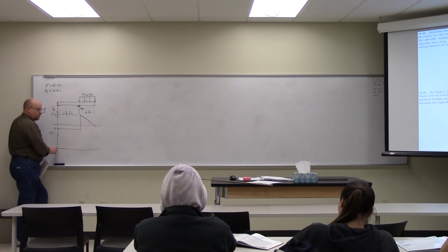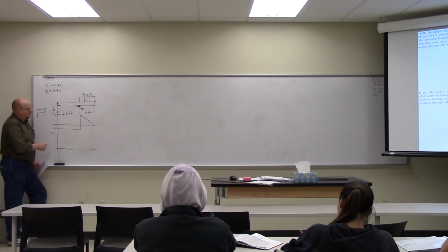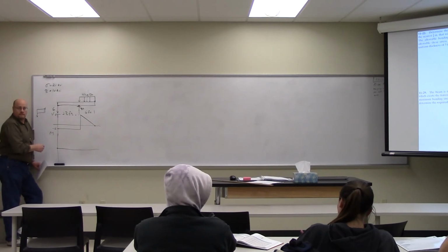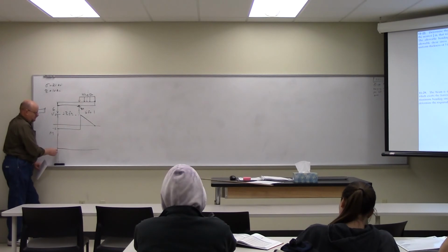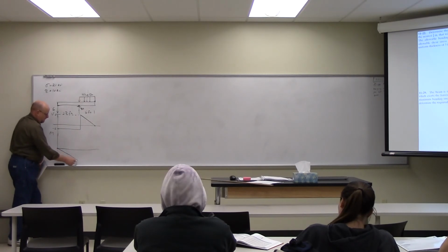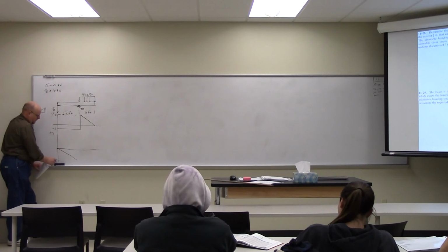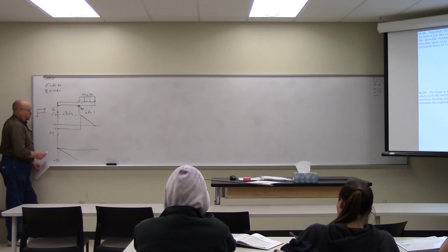Moment at the left starts out at 0, because there's nothing to support a moment. What do I do from there? Linearly decrease to 6 times 12, which is 72. -72. I apologize to those of you on video who can't see what I'm writing. Then what? Then it parabolically increases back to 0.